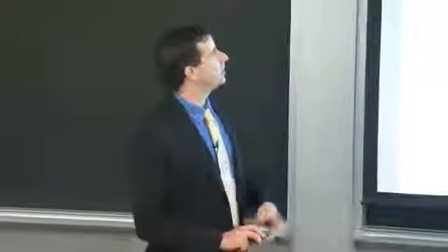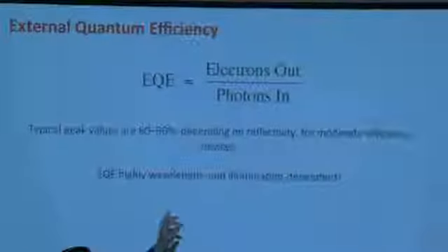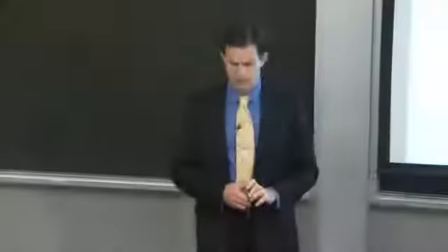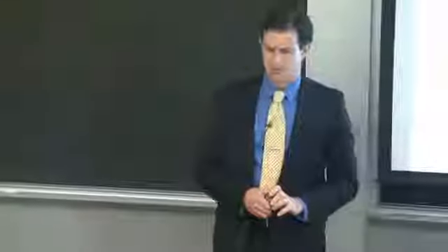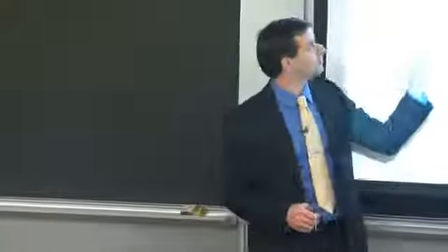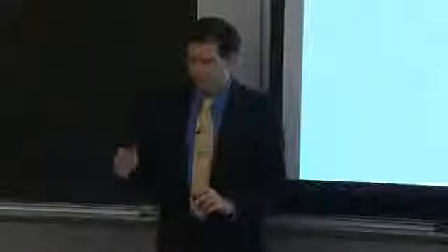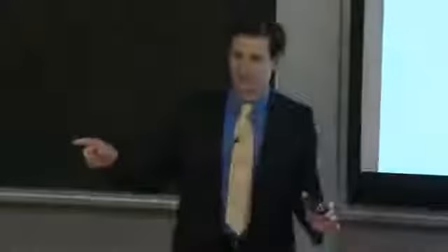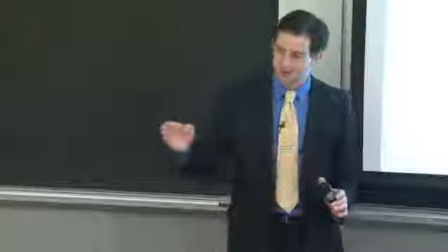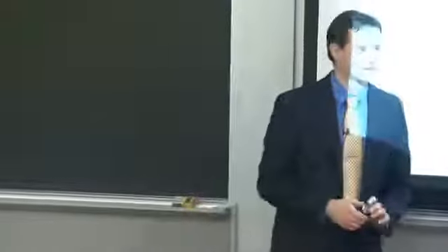In principle, you should have EQE as a function of lambda, really. And the photon in is going to be, obviously, at a certain wavelength, usually. I've rarely heard EQE given in a polychromatic sense, where they take an entire solar spectrum and measure the quantum efficiency average. Usually, quantum efficiency is measured wavelength by wavelength. And so you might change your monochromator settings 20 or 30 times over, or even more, over a quantum efficiency measurement to really map out the entire solar spectrum, from short wavelength in the ultraviolet all the way to longer wavelength in the infrared. And you're absolutely right.